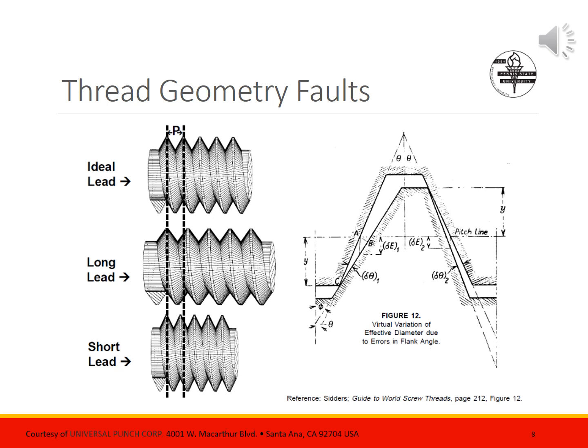The sketch on the right shows a thread form that might in fact have the desired pitch as well as the desired pitch diameter. Yet, because of its distorted shape, the errors in the flank angle would fail a thread gauge. This is a feature of any functional gauge. Functional gauges check to seek and uncover if parts will be interchangeable and function in an assembly. A threaded part with a large enough flank angle error will fail the functional thread gauge check for interchangeability.